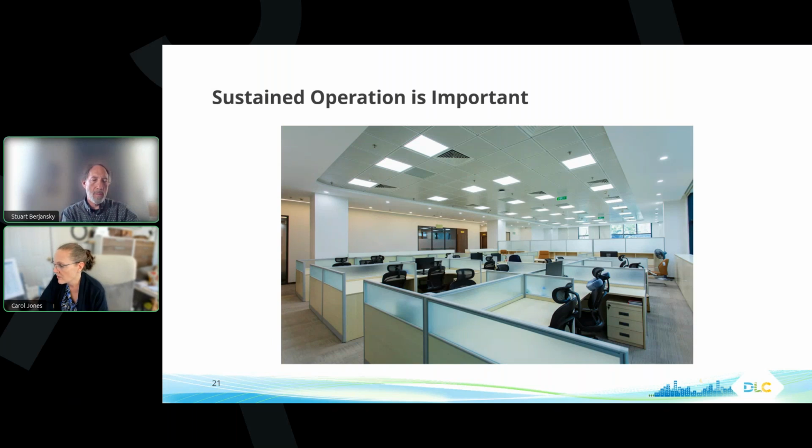So they need this information. Fault diagnostics is one of the things I want to make sure to mention. DALI has the ability to report on faults if there's a lighting fault. That's something that's well appreciated by the customers in the operations phase. It's mostly been HVAC, where people know what a fault is, there's information about what has gone wrong, and that's communicated digitally. That happens with DALI, so it's not just about, oh, something's wrong, pay attention to this fixture. It says there's a problem and here's what it is. So it gives you diagnostic information in addition to identifying where the errors are, and you only need one truck roll. I think we should in general pay more attention to what folks need in the operations phase.